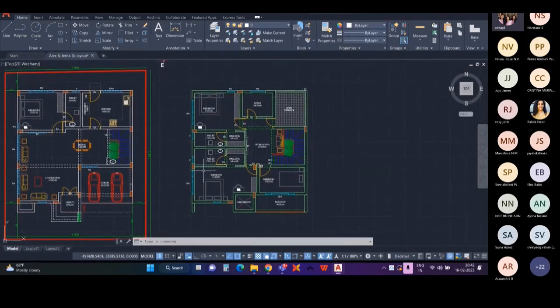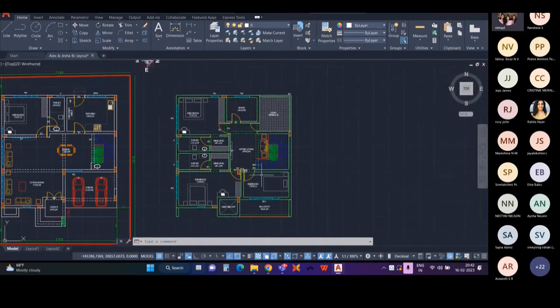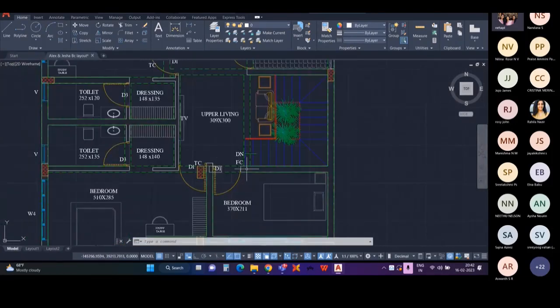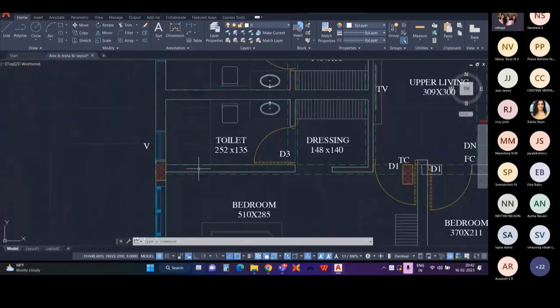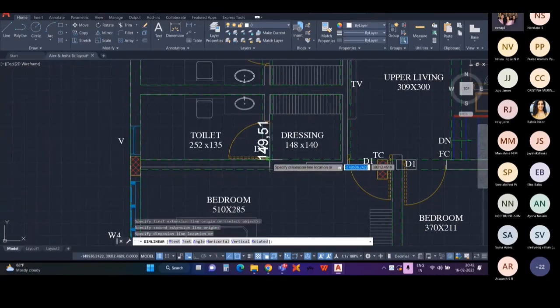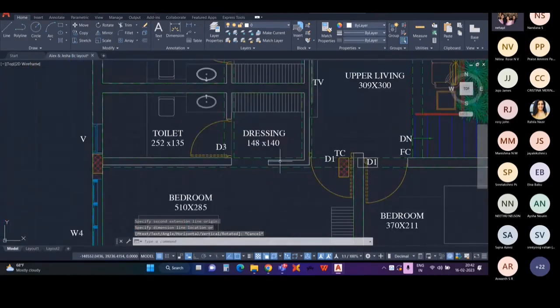When we look into the first floor, this column will be terminating at this portion. So there are no other columns at this portion, and we need to provide columns at the first floor level too. So we will be starting a floating column from the first floor. When we look into this wall, the wall size is less. It's not a 20 thick wall. It's just a 15 thick wall and this is a 10 thick wall.